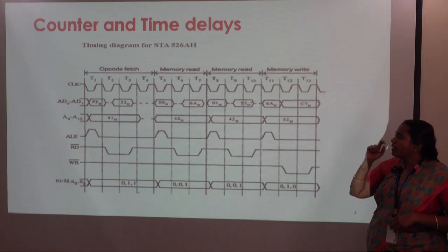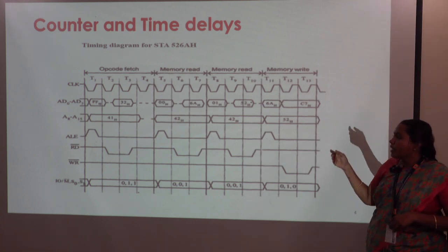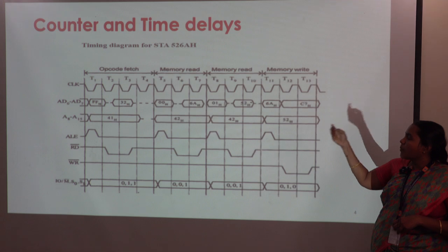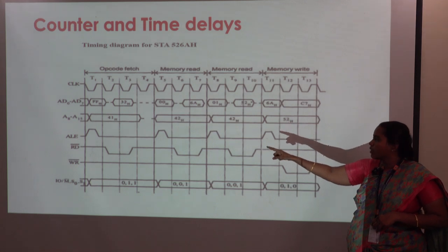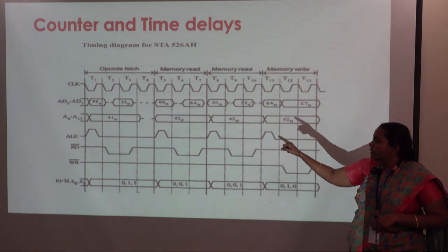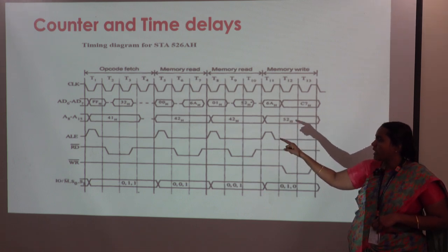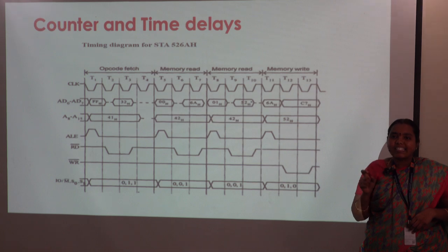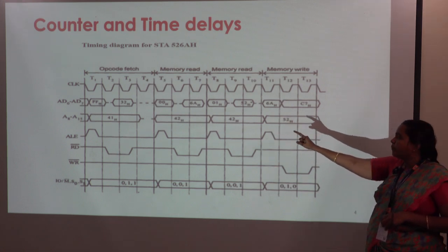First, we want to move the program which is at 41FF. At 41FF in the 8085, we want to store the opcode 32. 41 indicates the higher byte, FF is the lower byte. So we access memory 41FF and move the opcode 32 to that address. 32 is the opcode for STA. Next is 4200. 42 is the higher order byte, 00 is the lower order byte.